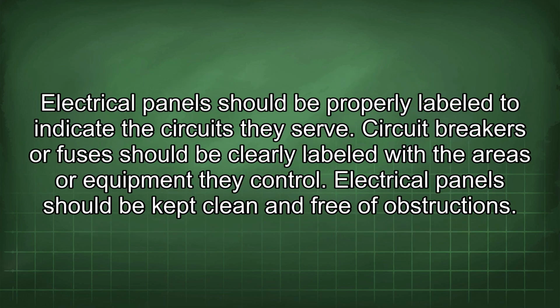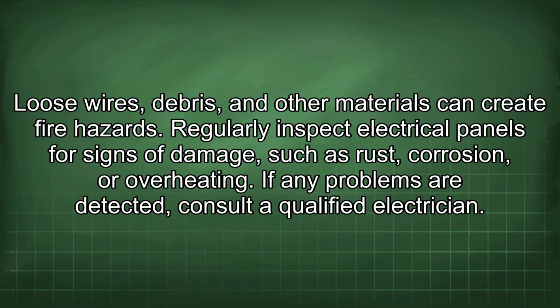Electrical panels should be properly labeled to indicate the circuits they serve. Circuit breakers or fuses should be clearly labeled with the areas or equipment they control. Electrical panels should be kept clean and free of obstruction. Loose wires, debris, and other materials can create fire hazards.